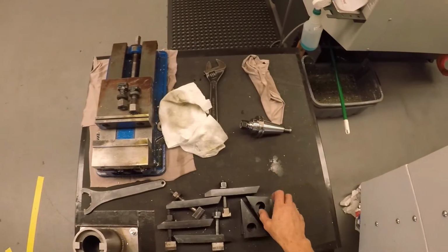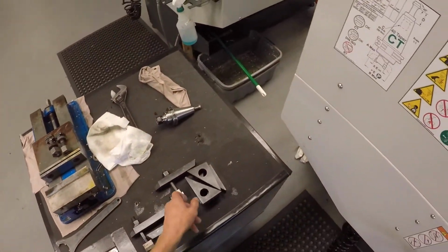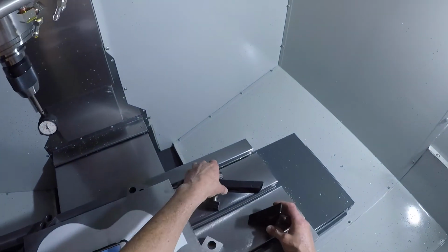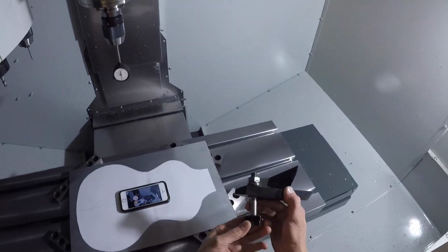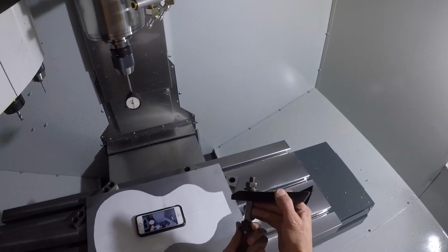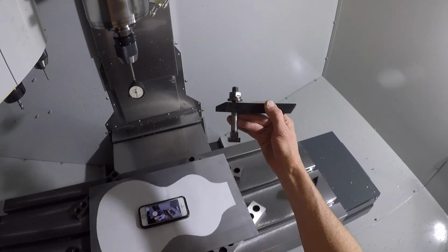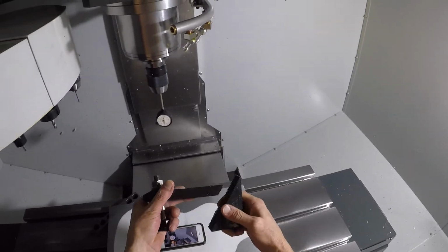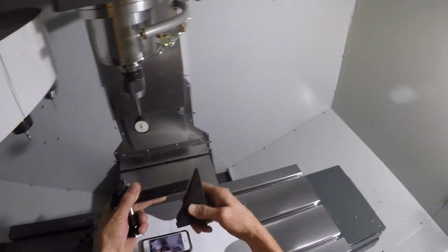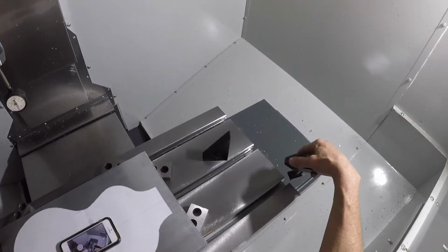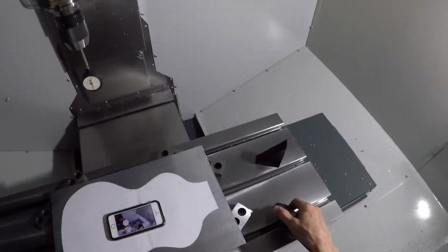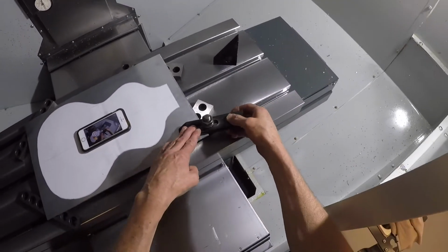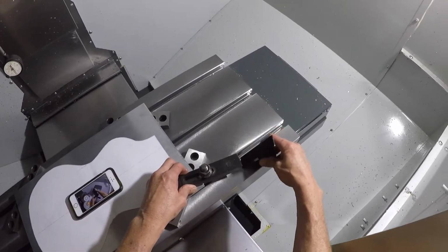These are called step blocks. And the way that they work is that there's a T slot, a T bolt. See this bolt there? I know the light isn't the greatest, at least there is light. And then there's the step block, and they kind of lock together like this. So I'm gonna slide the T bolt into the T slot and put this over my parallel.